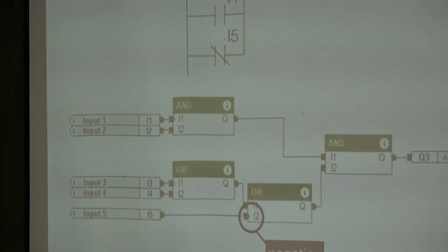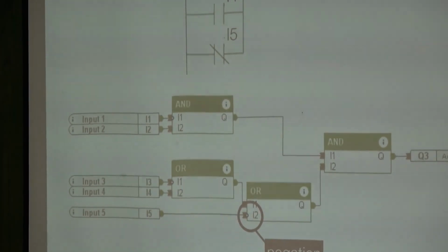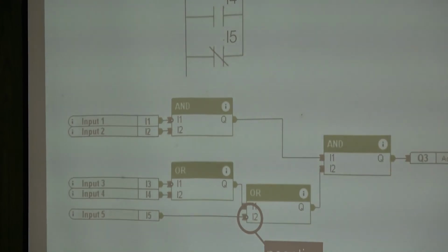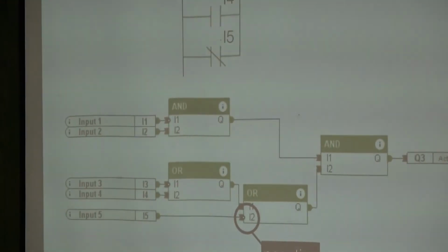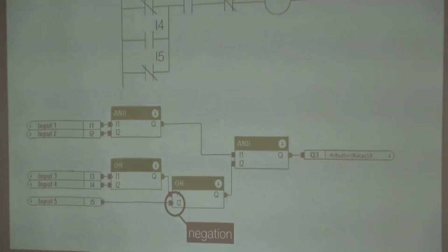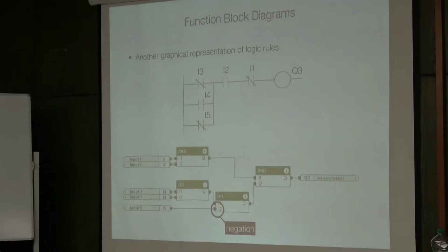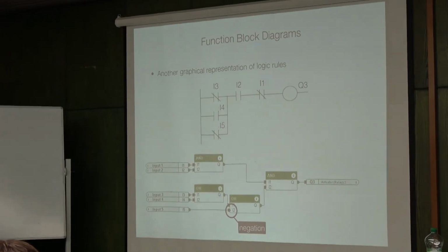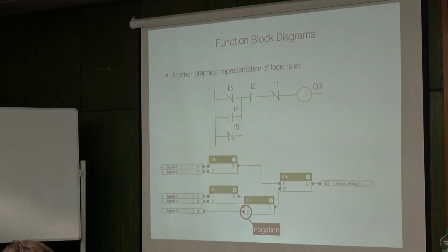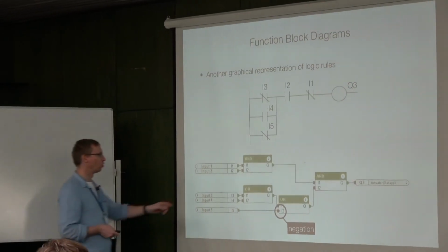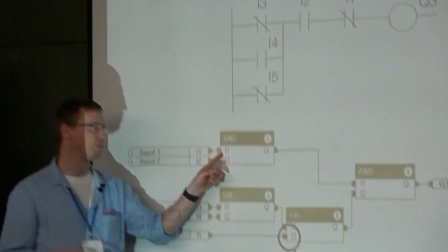But yet again, that's the sad reality of PLC programming. Every click, every typo in your code will not break your code. That's the bad thing about it. The compiler will not warn you, but it will just execute a different logic from what you have designed. So this little dot here and also the one here mean negation.